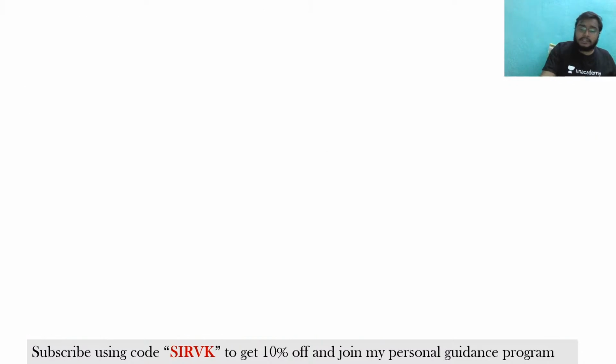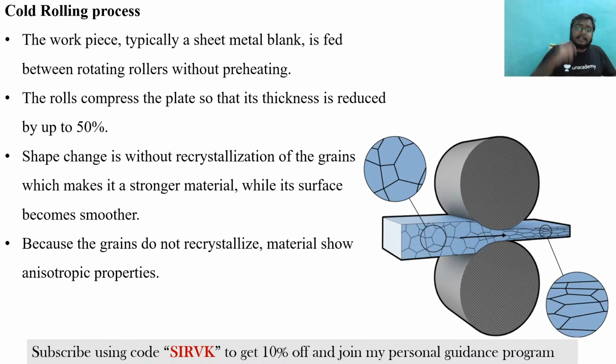Understand or not? Now see, whereas in this condition, with the rolls, what is happening? This is a cold working process, so there are no chances of marks. Any kind of mark will not be there, and definitely when no marks are there, my surface quality will enhance. Yes or no? And there is no problem of oxide layer also. Why? Because the temperature is very low.